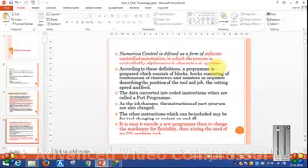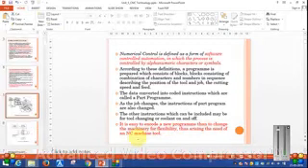Thus, according to this definition, a program is prepared which consists of blocks. A block consists of combinations of characters and numbers in sequence, and describes the position of the tool and job, the cutting speed and feed. The data is converted into coded instructions, which is called part programming, and it is very easy to encode new programs than to change the machinery, thus arising the need for NC machines.